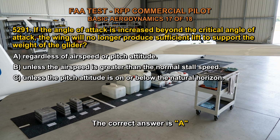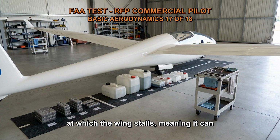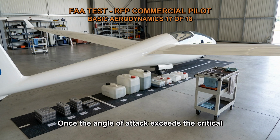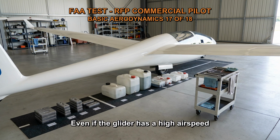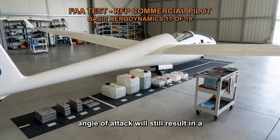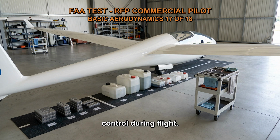The correct answer is A. The critical angle of attack is the angle at which the wing stalls, meaning it can no longer generate enough lift to support the weight of the glider. Once the angle of attack exceeds the critical angle of attack, the wing will stall and lose lift, regardless of the airspeed or pitch attitude. Even if the glider has a high airspeed or a nose-down pitch attitude, exceeding the critical angle of attack will still result in a loss of lift. It is important to avoid exceeding the critical angle of attack to maintain sufficient lift and control during flight.